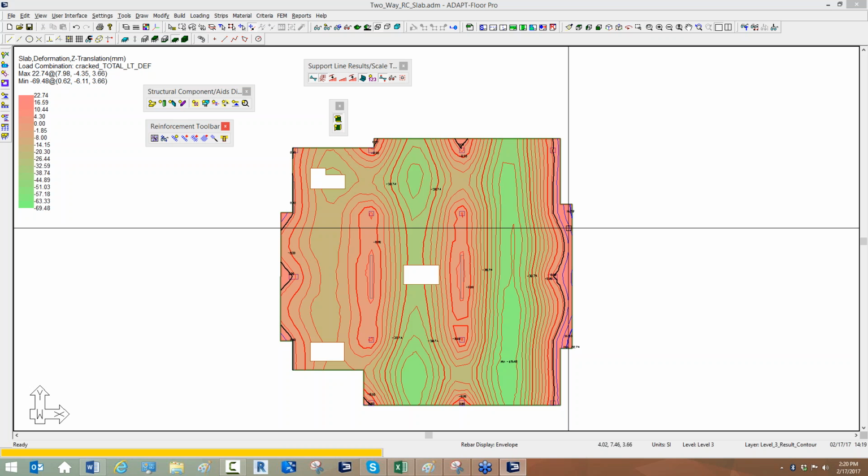Can we now copy the live load strips on different levels, the patterns? Pavel, the patterning, as you know, is really a byproduct of single level analysis. And when we built out the program for multi-level, it was never applied to a multi-level model. That's not to say it can't be done, but for doing live load skipping on a multi-level model, my recommendation is for you to set up unique skip regions on every level, and then you're going to have to create patterns on each level. Can you copy up the skip regions? You can. I would copy up the skip regions, but I would create new patterns because the patterns that were previously created belong to the floor below. So you can copy up the skip regions, but you have to define new patterns once you copy them up.